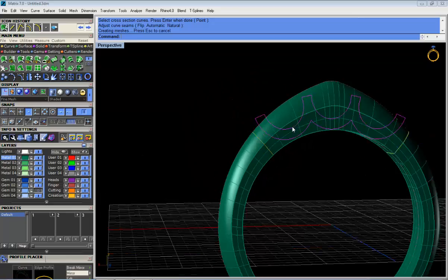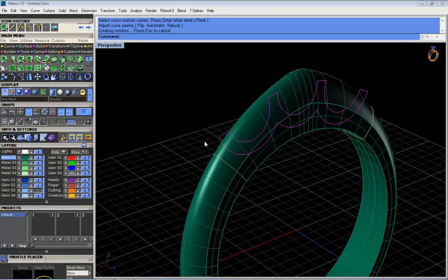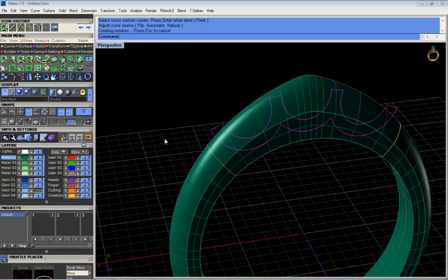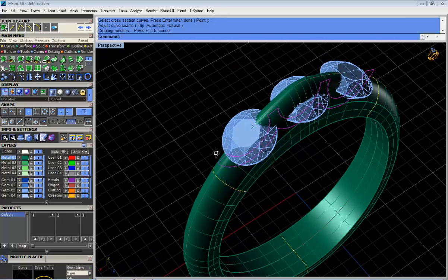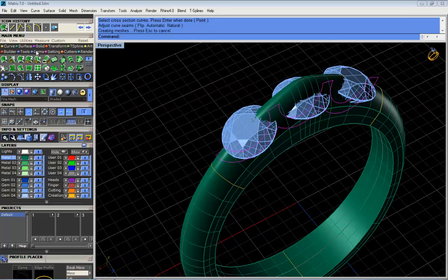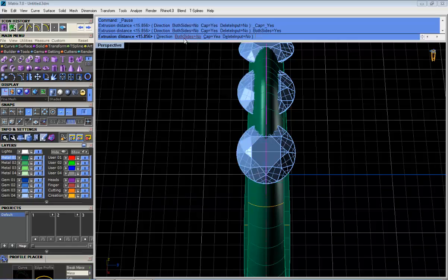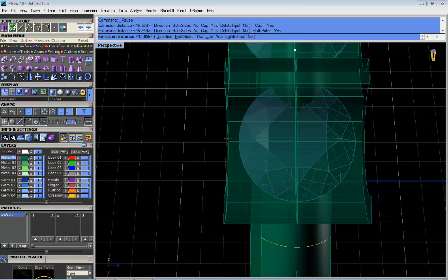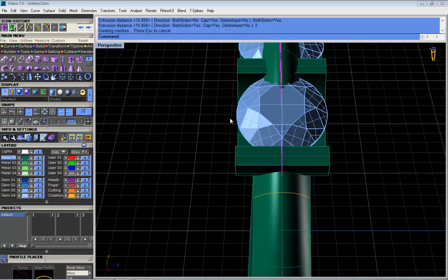What else? These are the curves that I've used to make the head. Okay, so basically I need to make it solid. To do so, I better show the gems before, just if it's better for you. And I'm gonna extrude that closed curve, solid, extrude. I'm gonna extrude it both sides up to this distance. This distance is basically 2. If I extrude 2, it's gonna extrude 2 in both sides. So now it's 4. 2 and 2.